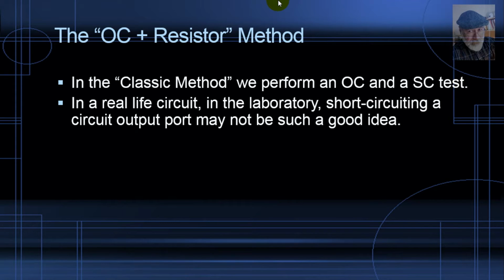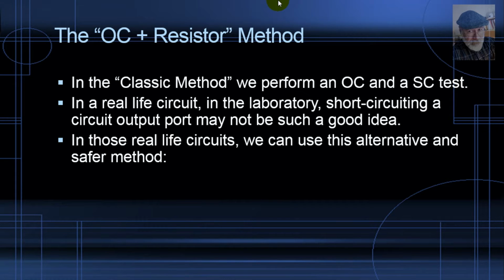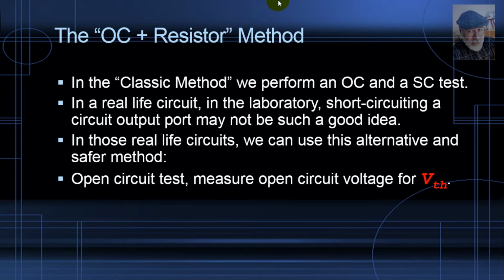In a real-life circuit, as I said, short-circuiting a circuit port may not be a great idea. In those real-life circuits, we can use this alternative and safer method. Open circuit test: we measure the open circuit voltage, and that is Vth directly. That is fine, same as before.